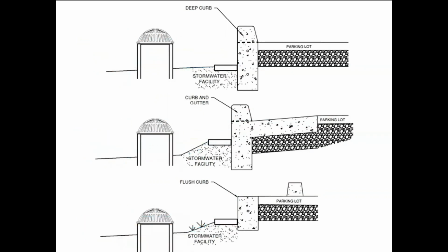So these are three simple, straightforward designs, but you need to be aware that the challenge comes by what happens at the other side, that is down at the other side of the retention systems. That's where a lot of people have difficulty because they're only focusing on the curb cuts and the raised drop inlets, and they're not focusing on what happens at the other side of a bioretention area, whether it is a berm or, more challenging, if it is a curb or the other part of the parking lot.